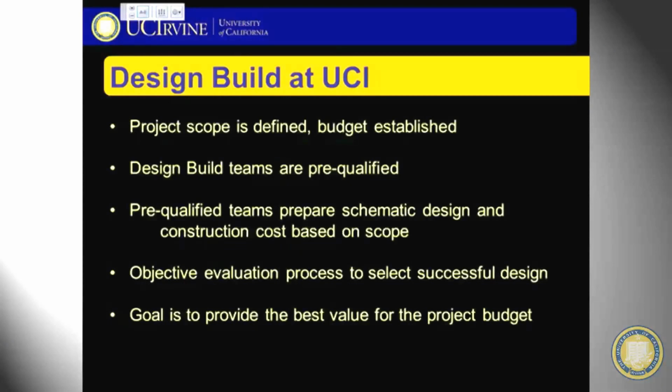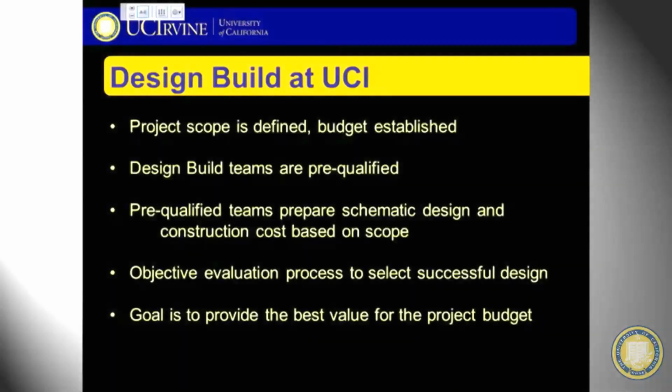Now what you see at design build is the project scope is identified and the budget is established. Then design build teams are pre-qualified. We advertise and they send us their qualifications, and we select usually 3 or 4 teams that are the best qualified to bid on the work. And what they do, rather than bid on plans that have already been prepared, they prepare a design that meets our project scope and our budget. It's kind of like a design competition, but it also involves money.